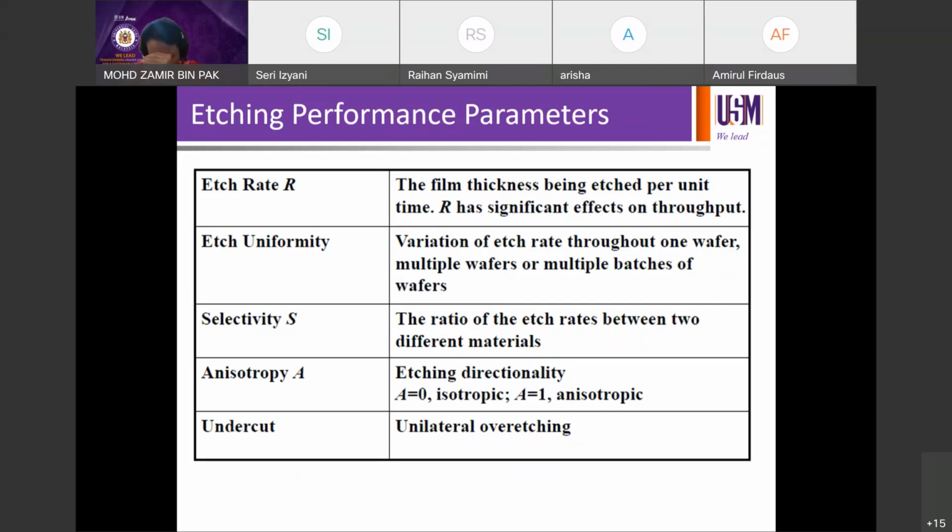If you can etch with a very high etch rate, you need less time to etch more materials. So your wafer per hour, remember, when you talk about throughput, we are talking about wafer per hour that you can process. In all processes, whether it's lithography, etching, implant, or diffusion, we are using the very same word, throughput, and that means wafer per hour.